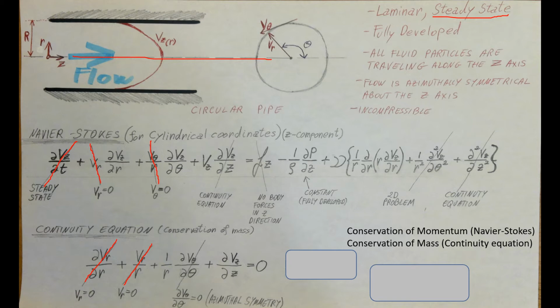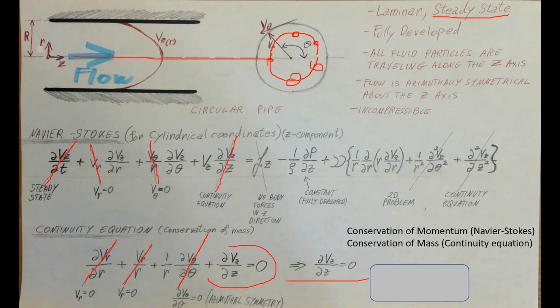Because of that, the change of V theta, that would be going around like this, doesn't matter, we take a point here, here, here, wherever, as we go around, it's symmetric, okay? Because of that, this term is cancelled. And what we have left is what we've been looking for. There it is. We can come back to the Navier-Stokes and cross it out. Okay. Next up, Fz.